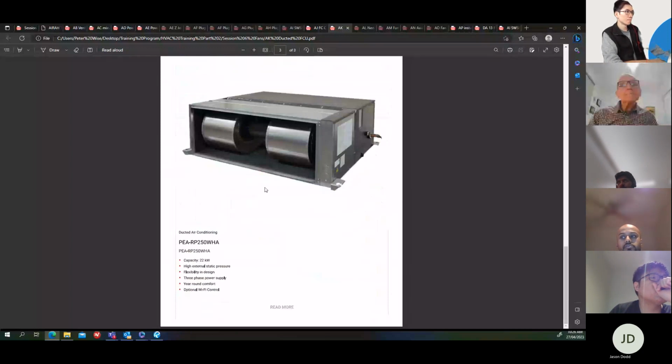So fan motors for single inlet and double inlet fans are normally 3-phase squirrel cage induction motors, and the motor speed is normally 4 pole. The speed of the fan is set by fan and motor pulley selections. So when you purchase a fan, you tell them what flow and pressure you need, and the manufacturer will decide what the pulley sizes need to be and the belts to drive.